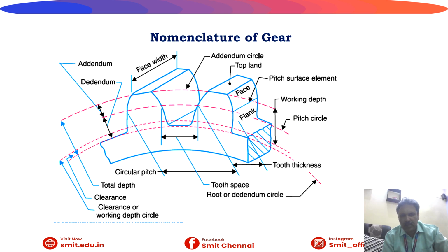Circular pitch is nothing but, it is highlighted in the diagram also, the starting of one tooth to the start of the next tooth, that is called the circular pitch. And the tooth thickness is also given over there, and the working depth: the gear penetrates up to the level at which it is engaged with the mating gear, and that is called the working depth.